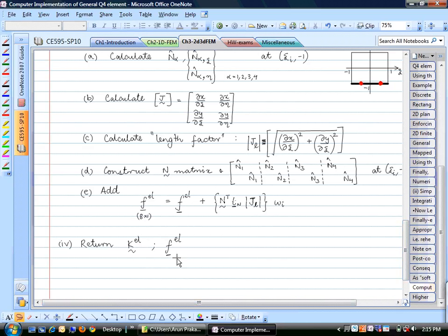All right, so at the end of this, once you have calculated all your body terms and all your boundary terms, domain and boundary terms, at that point you should have your correct element stiffness matrix. And again, these are all estimates. These are approximate K element, approximate F element. This is different from CST, where in the 3-noded triangle, you had the exact K element and the exact F element. But if you have distortion in your elements, these will not be exact. These will be approximate.